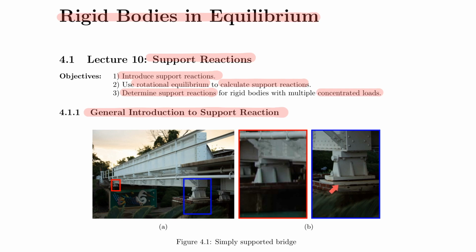You can see that on the concrete, which builds the foundation, if you will, for this type of bridge, there's a steel plate. And then on top of that steel plate, you have something that can actually rotate or move because there is effectively a hinge here. We'll talk more about hinges later, but you see there's a bolt here, so this entire contraption on the bottom can actually move about this point, and this part is also not connected to the bottom steel plate here.